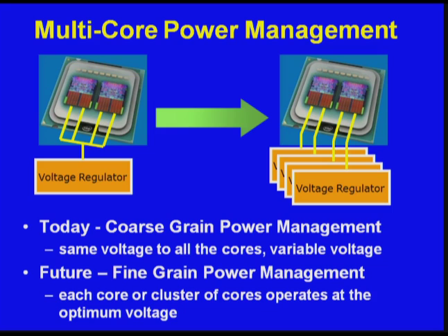So ultimately, what is going to be needed down the road, whether sooner or later, is voltage regulators that are integrated on the die or on the package, and not on the PC board, in order to reduce all that latency, reduce the losses involved, reduce the amount of wiring you need, and so forth. So to that end, that is what I'm going to be talking about.